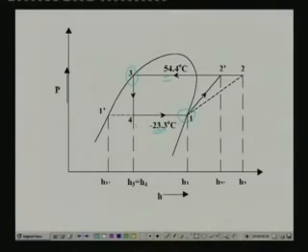Once you say that it is saturated vapor and temperature is specified, we can immediately locate the point and find out the enthalpy H1, the specific volume, the entropy, and all the properties can be obtained at this point. Similarly, all the properties at point 3 can be obtained just from this temperature and the quality, because it is a saturated liquid. So, these properties also can be obtained directly from the refrigerant database, or if you have a pH chart, you can directly locate these points.